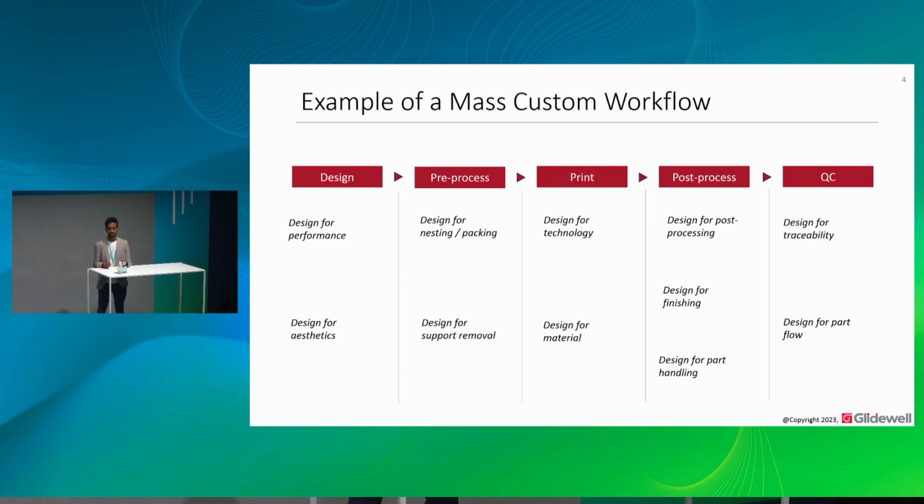but also based on how big your vapor smoothing process is and maybe some of the other parts that you're smoothing, you can actually decide how you want the part to be oriented within that smoothing process. So you can decide whether you want them stacked vertically, horizontally, what the spacing between some of these parts is. Some of this can also be based on just the performance of your smoothing machine, right? So it comes down to the interaction of the solvent with your TPU material. So we have that process, we have the eyelet or the fish hook that's been added. The next step is a dyeing process, which again, everything we did for vapor smoothing applies, so I'm not going to touch that too much.